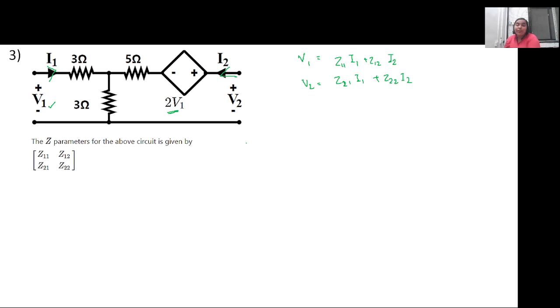So this is how we will rearrange the equations if we simply use KVL or KCL to write down whatever the circuit conditions are. In this case, I1 current is flowing in this way, I2 current is flowing in this way. Using KCL, both are going into the node, so the net current coming out of this particular node is I1 plus I2. Is this fine? Yes, ma'am.